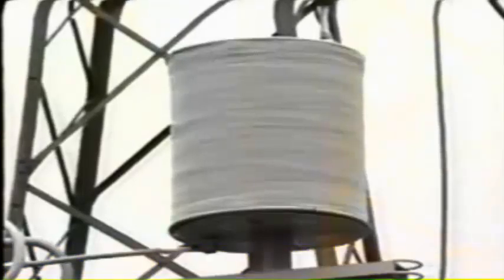First, let's go into the switchyard and look at the line hardware. This piece of equipment, which is connected in series with the line, is called a line trap or wave trap. The line trap may be mounted vertically or horizontally, like this. The simplest type consists of a large coil, that is, an inductor, made of conductor material and capable of carrying high load current. It must also be able to withstand very high values of fault current for short periods of time.